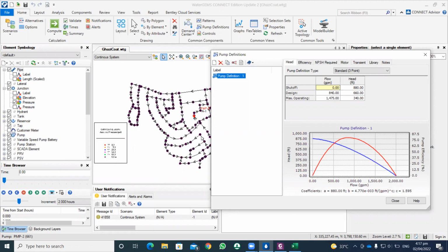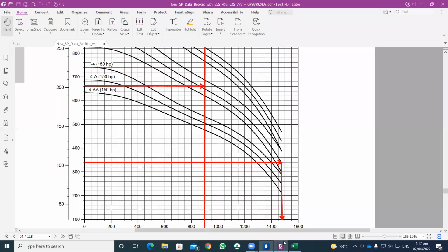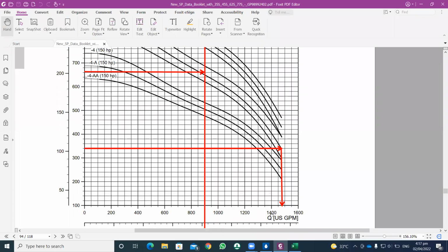Therefore, you should consider that point as well, the yielding of water or the discharge of water from a reservoir. And then I put a value of the maximum operating point, having a capacity of about 475 gallons per minute, giving a head of about 340 feet.